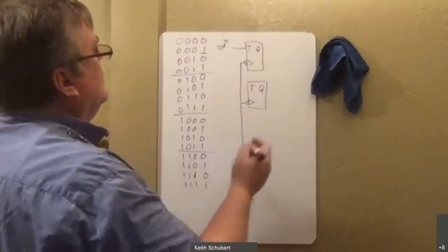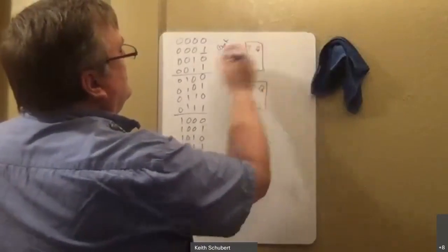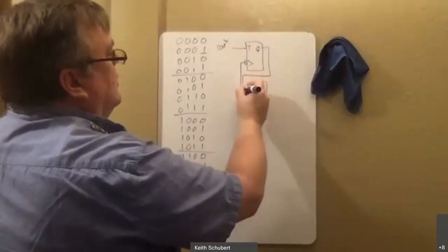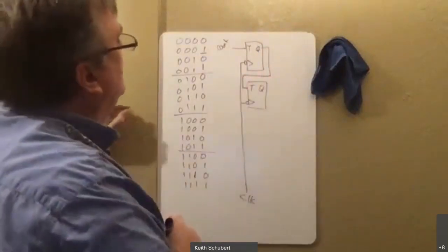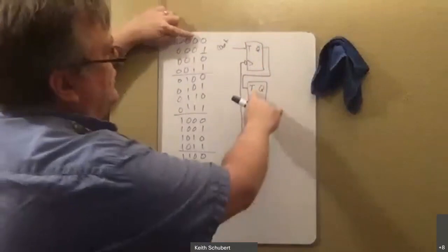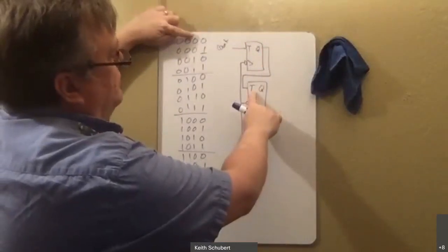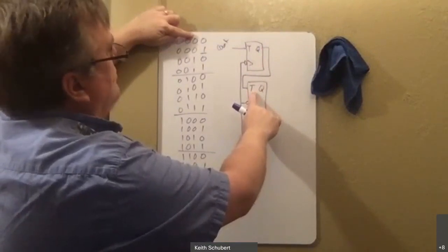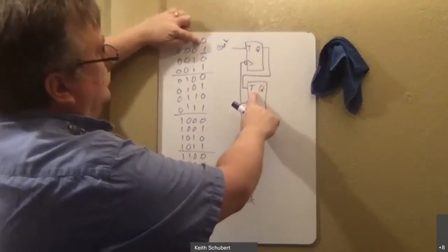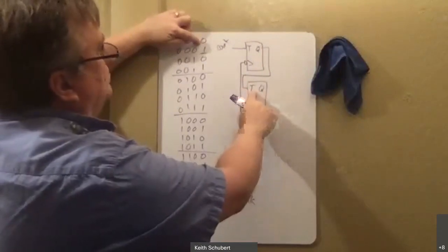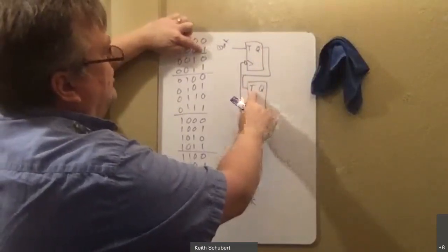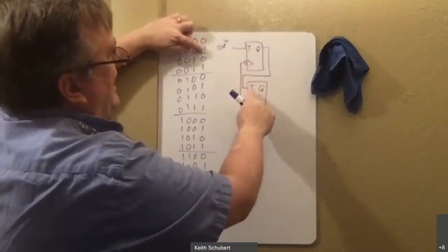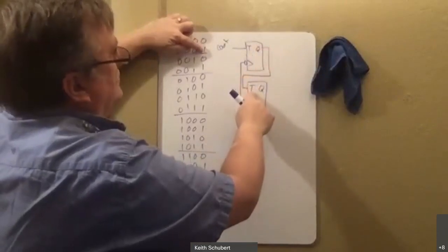So now if this is only a 1 for one time period. So imagine I did this. At this time instant, this toggle is turned off, right? Because it's 0 on that bit. Therefore, this is a 0, so this doesn't change. When this becomes a 1, this happens at the clock pulse. So this is after the clock pulse. It takes a little time to come down.